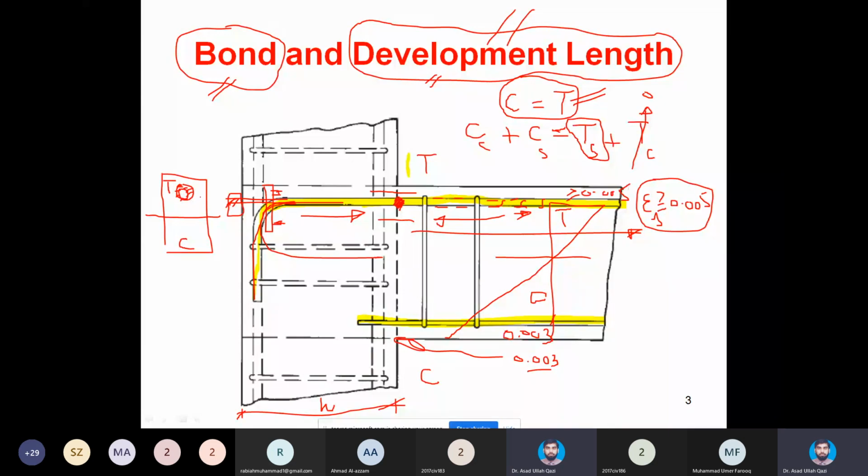It is just like before concreting, you grease the bars with oil or some greasing component. You have actually tried to intensely debond the steel from the concrete. So this is not a right approach to debond the bars from the concrete. So friction between the steel and concrete at the contact area, natural chemical adhesion between steel material and concrete paste, and moreover the deformations on the deformed bars are the key components which are developing the bond.